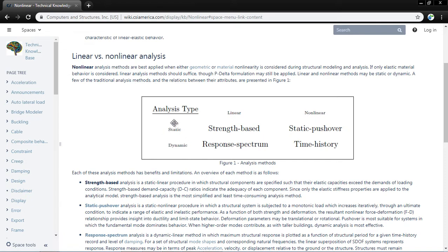And there are again two: static load and dynamic load. Static load is the load which does not change with time, and dynamic load is the load which changes with respect to time. In the static load, you can consider the load points which you apply in the form of values to the structure. And in the dynamic, you have to provide the whole history record, for example, acceleration versus time, velocity versus time. So all these things that depend on time are dynamic loading.